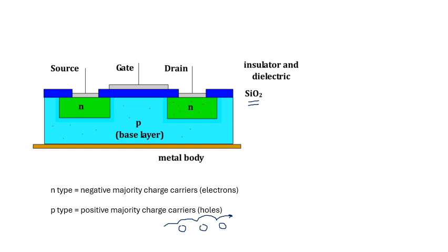That is an insulating material, and it also acts as a dielectric. This is my metal oxide. Silicon is not really a metal, but it's a bit metally; we call it a metalloid in chemistry. But anyway, that is your metal oxide layer, the silicon dioxide, and that acts as the dielectric for the capacitor.